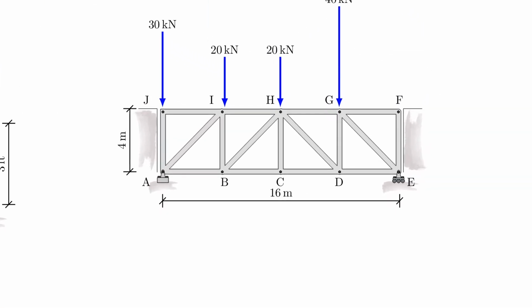So this one here on the top, what do we have going on here? I would say we definitely have a zero force member here because parallel and an unloaded third one. So let me make that disappear. That's gone now. Do I have another one? Yes, I do, and that's a little bit deceiving again. I actually have two more ones because here I have the second case that we discussed, and that is the external unloaded node here.